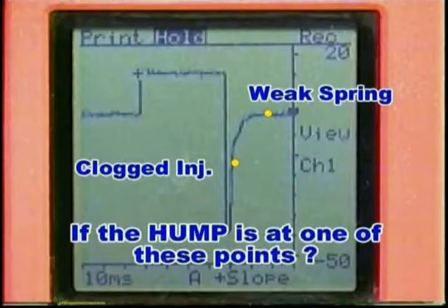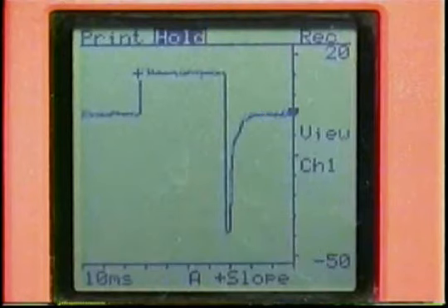These readings, however, should only be used as preliminary indicators of a problem. Always follow up on these diagnostic tests with further manual testing to prove your faulty issue. This also includes an injector leak down test and carefully monitoring the fuel pressure drop. A manual injector leak down pressure drop differential of 1 psi points to a clogged injector unit.